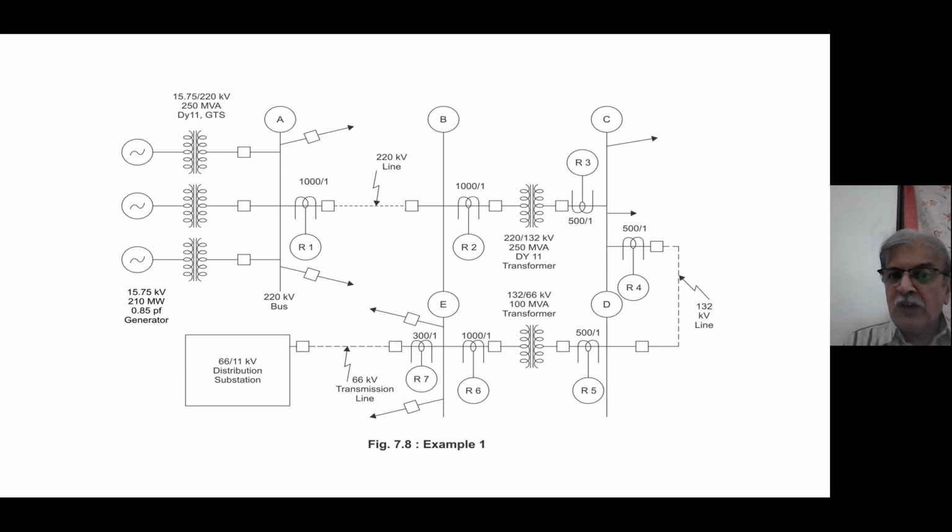So I have to find out time of operation of R7. For what? For the worst fault current. What is the worst fault current? Worst fault current is at bus E for R6 and R7, my dear friend, at bus E, because faulted bus E and just after breaker of R7 does not make much difference, hardly 1 or 2 ampere difference. The faulted bus E is 2400 ampere, fault after breaker is 2399 ampere. You see, it is nothing, negligible, because breaker is hardly 10 meters away.